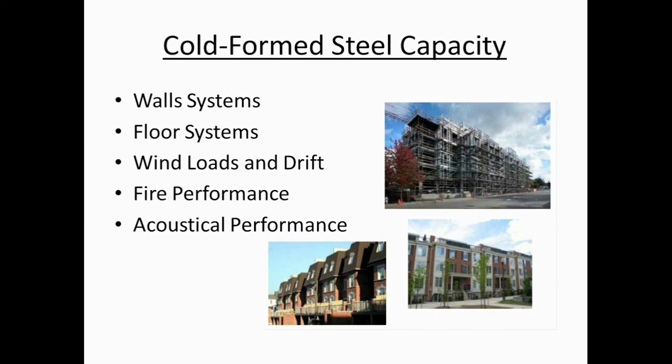We'll talk a little bit about that, and this is accomplished through simple things like shear walls and floor diaphragms. We'll look into fire performance of the various systems for walls and floors and show that cold-formed steel is non-combustible and is in its element, if you will, in mid-rise construction for fire and acoustic performance.